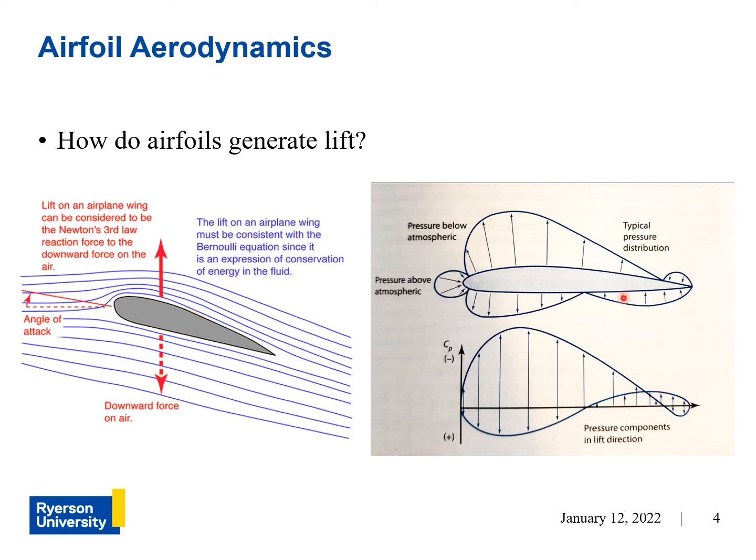So the takeaway from that is that there's a pitching moment here caused by the aerodynamics, as you can see from these arrows. And if there was to be any damage to the airfoil, the most critical area would be the upper surface, because that is where most of the lift is generated by the airfoil. And in fact, typically it's about 2/3 of the lift. So that's why it's very critical that this surface here remains undamaged.